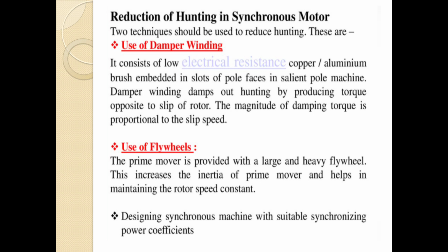Use of a flywheel. The prime mover is provided with a large and heavy flywheel. This increases the inertia of the prime mover and helps maintain the rotor speed constant. Another method is designing the synchronous machine with a suitable synchronizing power coefficient.